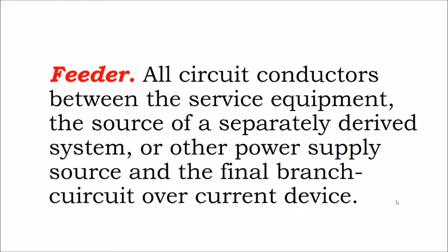All right, let's define a term. Feeder: all circuit conductors between the service equipment, the source of a separately derived system, or other power supply source and the final branch circuit overcurrent device. So what we're talking about is anything between the generator and the breaker switch on the panel that the generator provides. That's a feeder circuit.